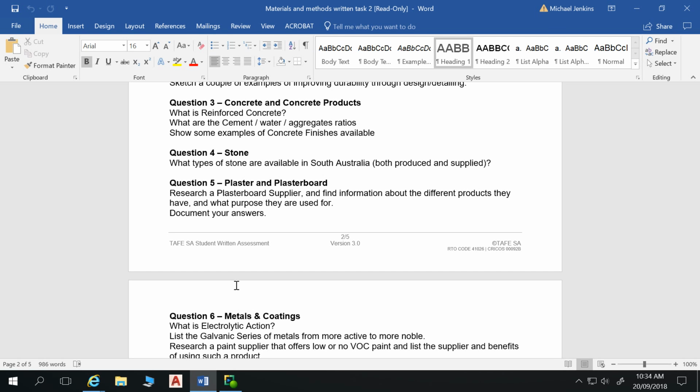If I am going to be casting these floors, I'll want much higher strength concrete, and I'll work that all down. So the golden rule for your concrete strength relates predominantly to your cement water ratios.